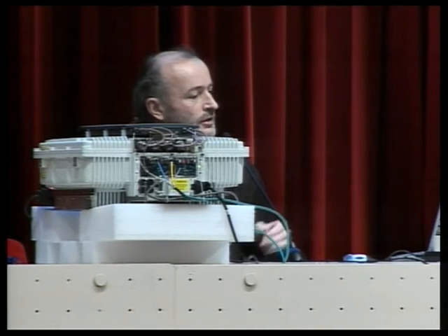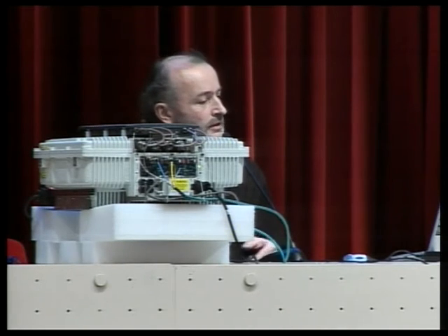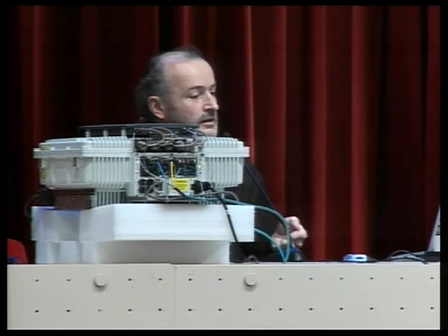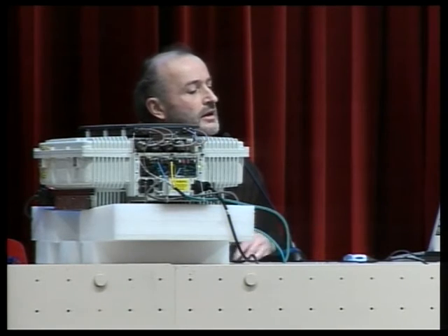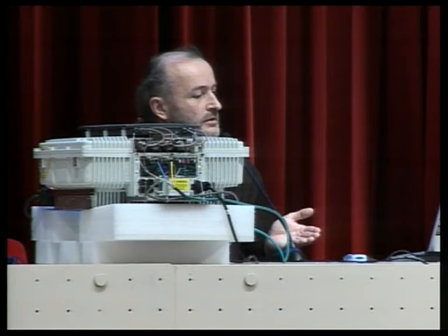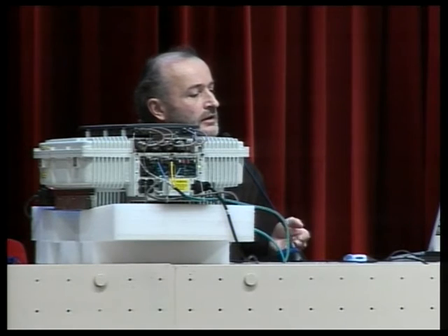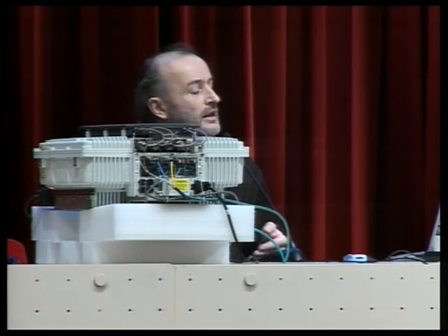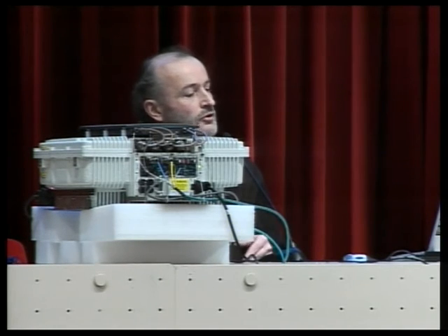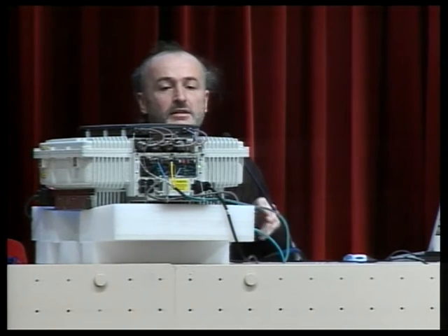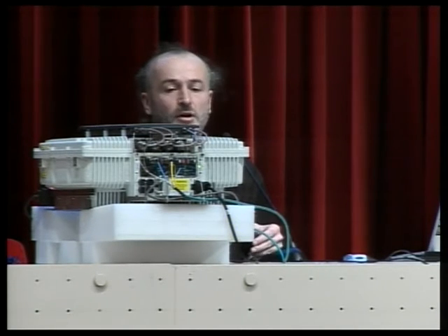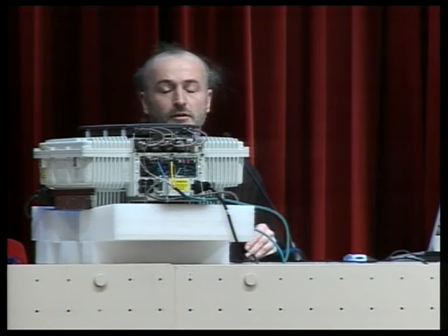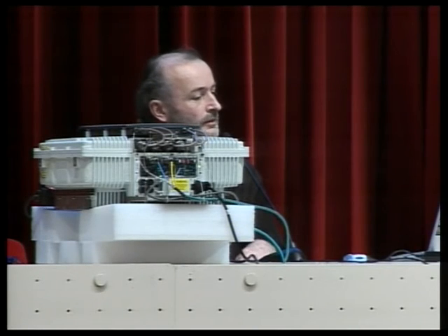In GSM, speech is compressed using several codecs. The most common ones are full rate and half rate. Full rate is 16 kilobits, and half rate is, as it says, the half one, 8 kilobits. And we have also several newer and better codecs. For example, there is the enhanced speech codec, but in our case, we only talk about the full rate codec because this is what we have implemented so far and which is also supported by our base station.